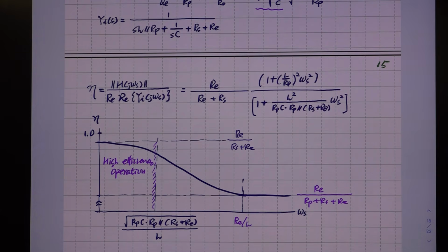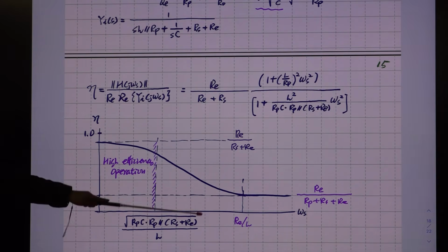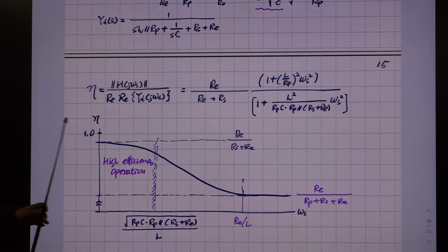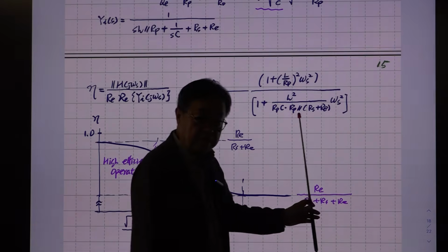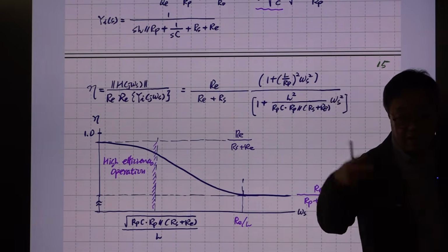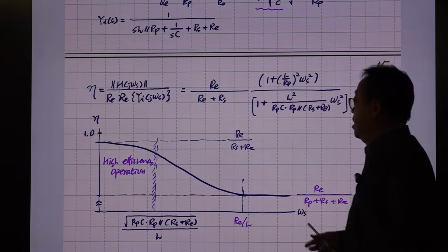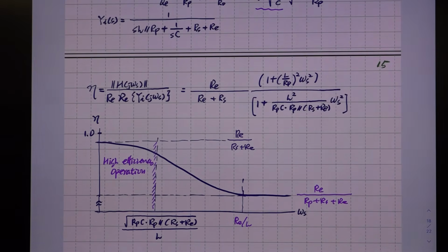So this curve depends on the resonant tank circuit, but numerically you can easily plot this and estimate the efficiency of your converter at different switching frequencies graphically. That is the second use of that AC model, and there are many other utilities of that model. It carries the essential critical information about the inverter, which is the same as the converter.